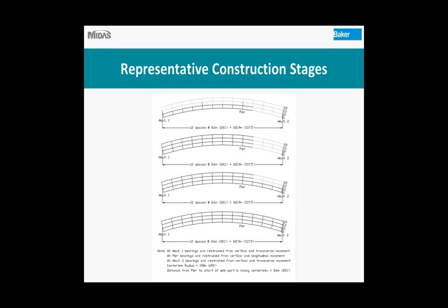If you go down to the next diagram, we've placed girders 3 and 4 from abutment 1 to a little bit past the pier. In stage 3, we placed the remaining sections of girders 1 and 2, and then finally we complete the steel erection. Like I said, this is representing the paired inner construction, where we place 2 girders at a time and we start at the interior of the bridge.